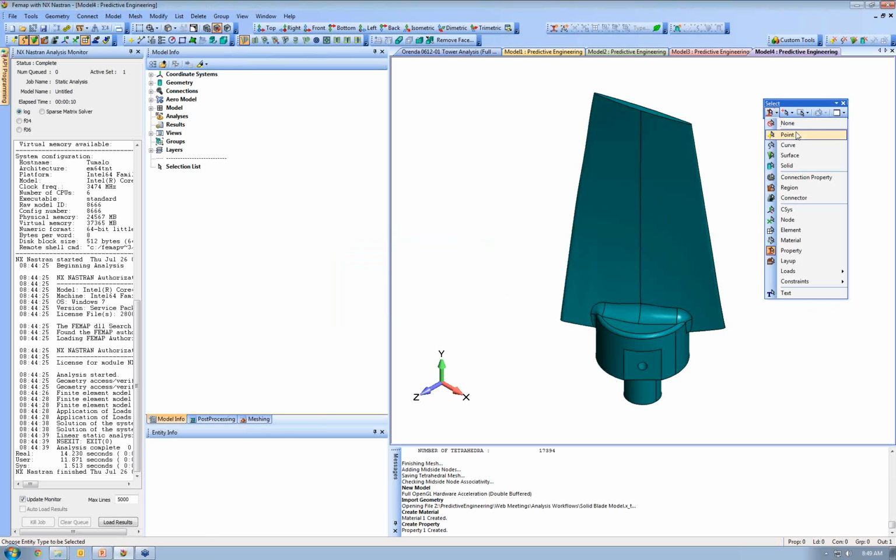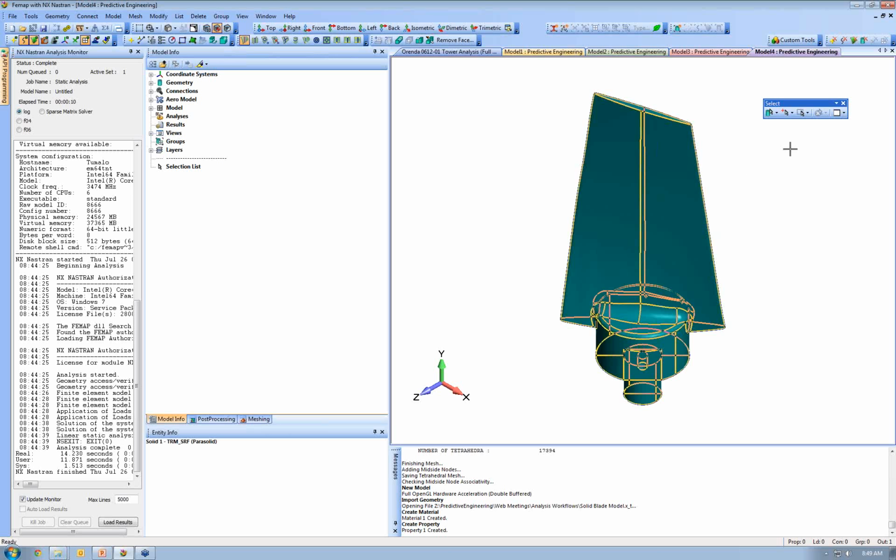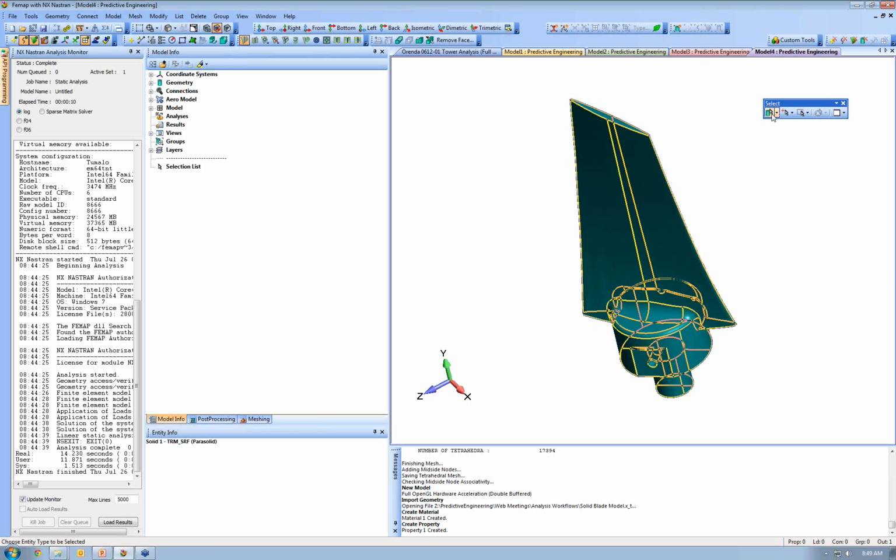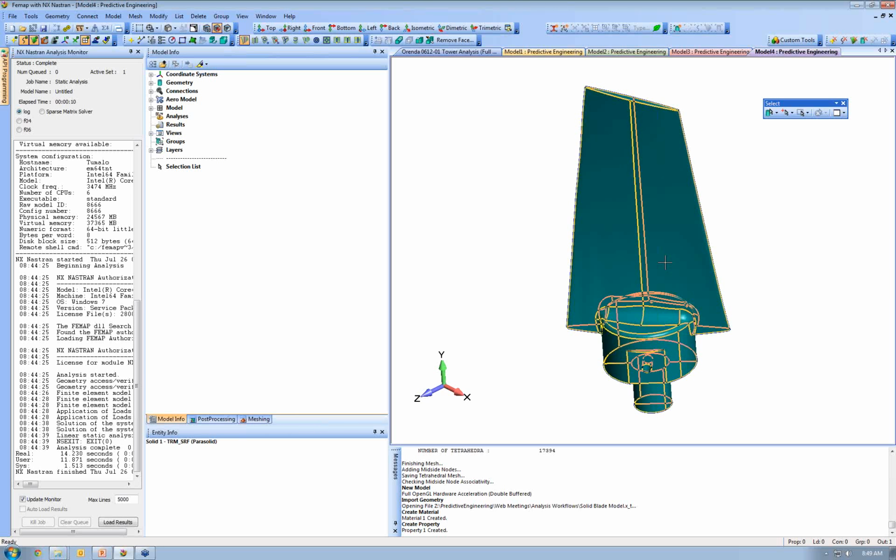We go to mesh sizing, and you'll notice this could be a little misleading depending on how you think of these workflows. You could go to elements, but I don't have any elements, so I can't affect my elements. I want to go to solid, because if you think about the tree, you would set your mesh sizing on your solid. You pick the entity that you want to control, which in this case is a solid. Now I actually have the entity for which my selector is set.